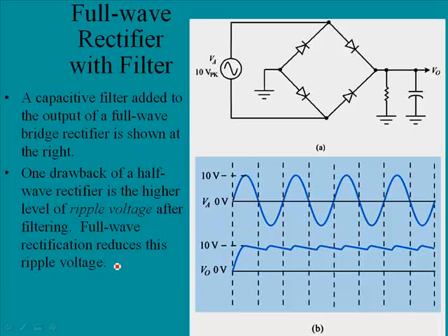Now, what you'll have with a full wave rectifier, remember that our output is going to look like this. I'll draw here. Remember, with full wave output, we don't have half wave, we just had 1 and then 1 and then 1. And with a full wave, there is less time for this capacitor to discharge.